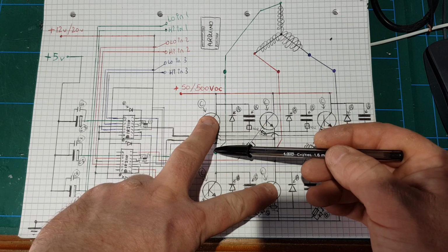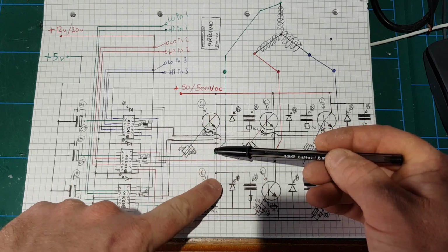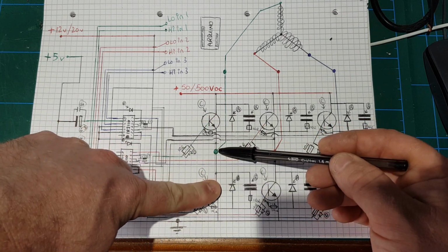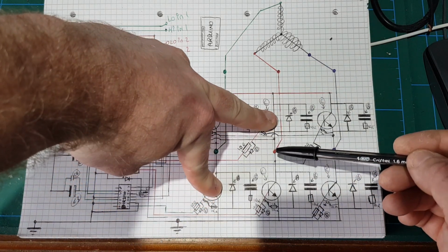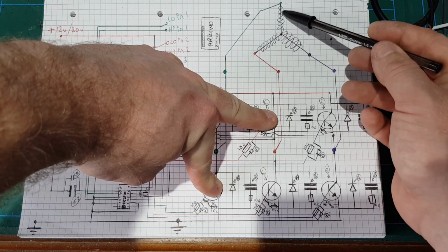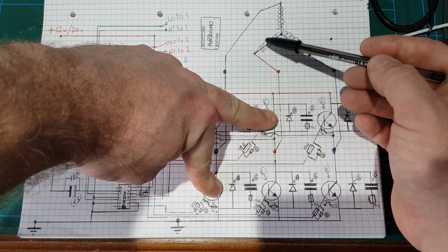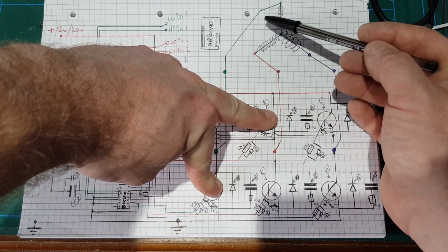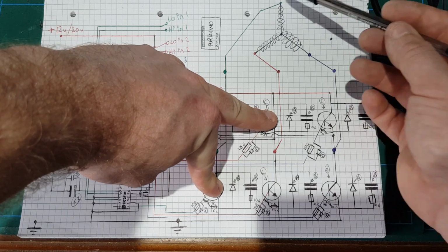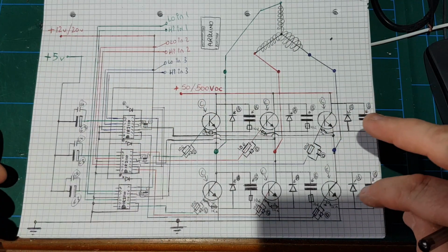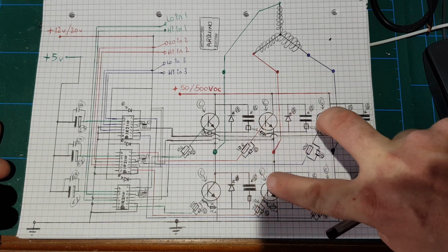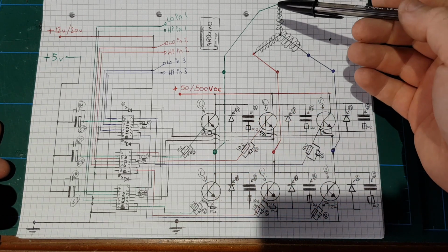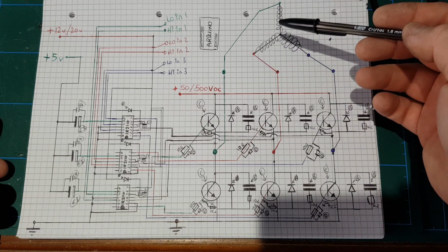We would make this one negative, which would be that one, because that's the negative rail. And we want this one to be positive, so it's now these two. So that's energizing the same coil the other way around. So now that's positive and that's negative. And essentially, using a combination of these 6 switches, you can energize any coil you want in any direction.